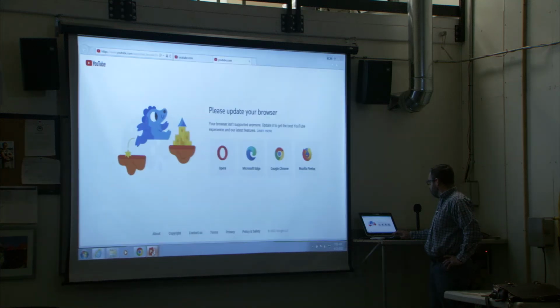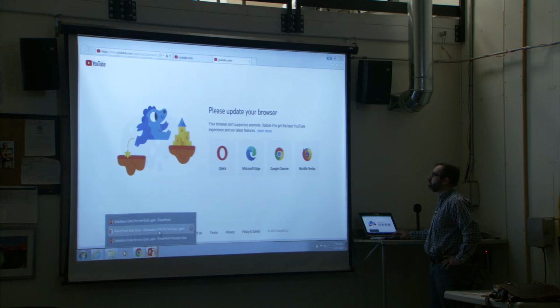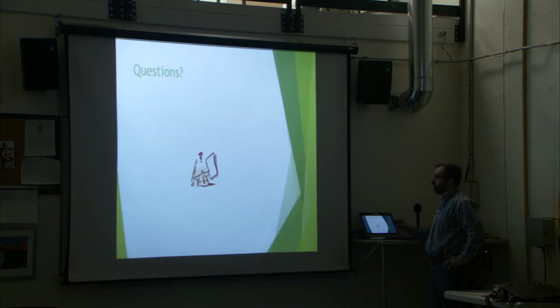so that is the presentation. Are there any questions? No? That fail point on there, we saw that glass, likely atomized oil coming out of the tap changer. Yeah. And in combination with the pressure leak on the transformer tank itself.